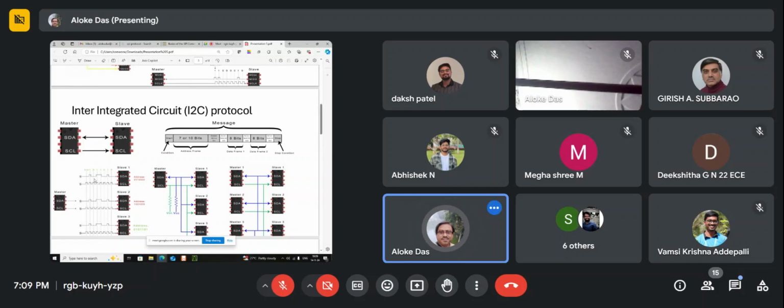This is again available. And again, this is the data. And this is the clock reference, very important. See, this is the clock reference. So at each clock edge, what is the value of this line? 0. That means it will accept the first bit as 0. Again, this is the rising edge of the clock. What is the value of this? This is 1. Then 0, 1, it will register. Like that, at each rising edge, the value of this line will form the data actually.